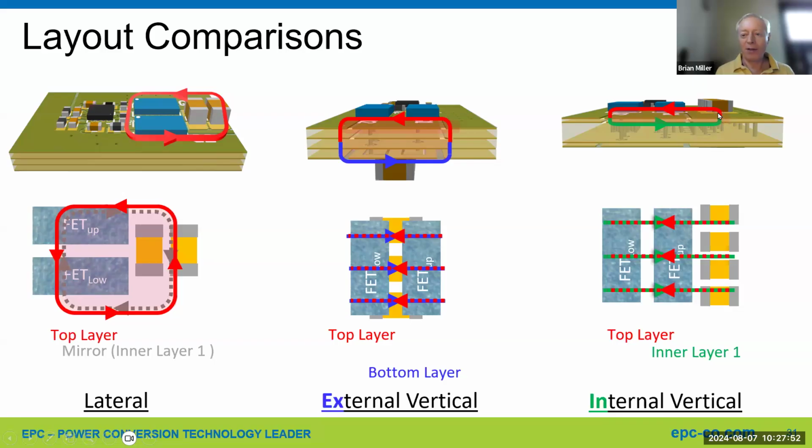It really reduces the total inductance. It shows coming from this point at the end, but many FETs have pins in the middle. So the return ground loop can actually start in the middle of the bottom FET in many cases, go down and around.